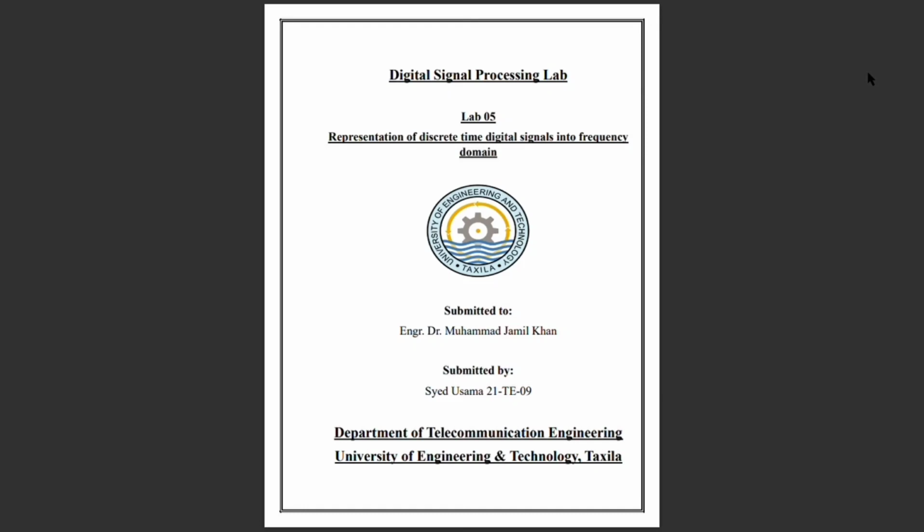Representation of discrete time digital signals in frequency domain. The objectives of this lab are: first, representation of discrete time digital signals in frequency domain. Second is resolution of spectrum. Third is computation of magnitude, phase and power spectrum. And the fourth one is spectrum leaking and avoiding spectrum leaking.